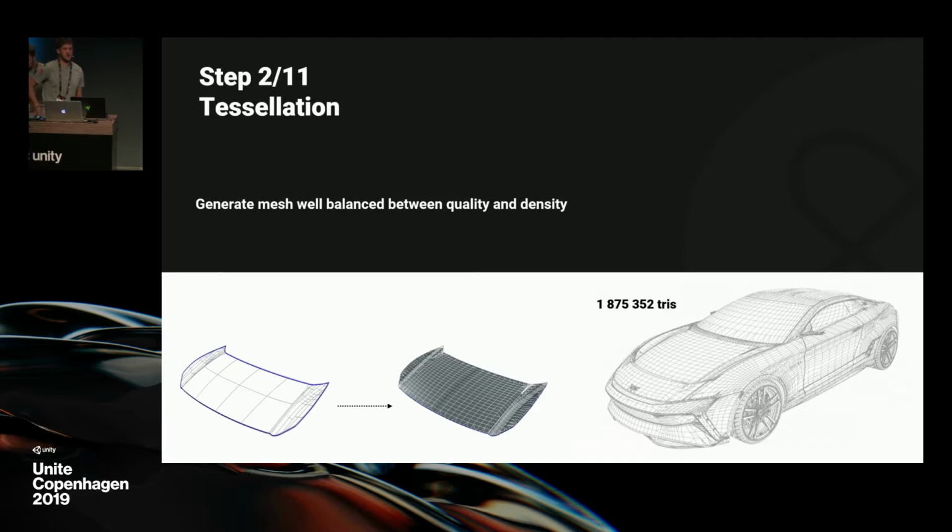So tessellation is one of the most important steps in data preparation, and it's one of our strengths at PiXYZ. From this mathematical BREP information we retrieve at import, PiXYZ has the ability to generate a watertight mesh that will be well balanced between polygon density and shape accuracy.